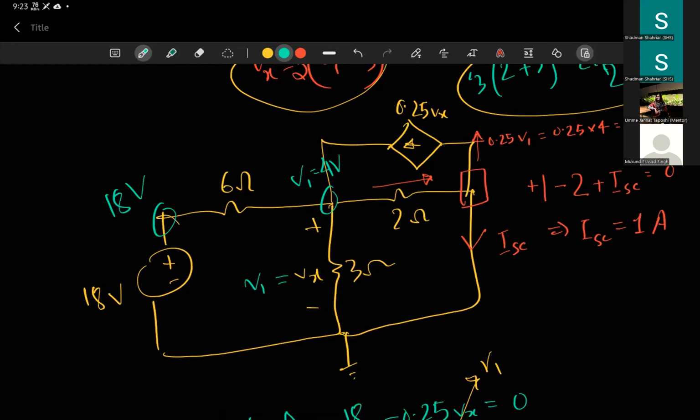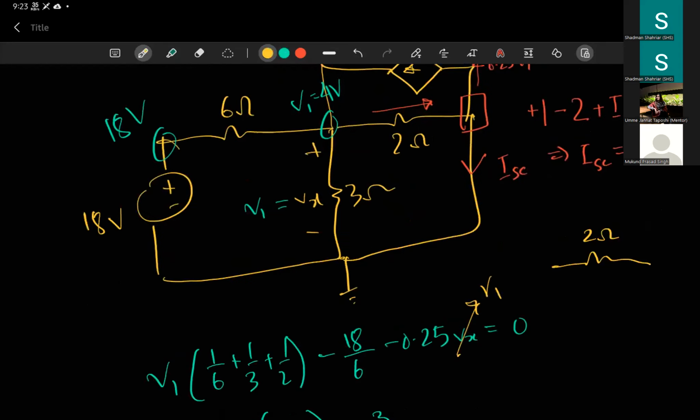The voltage here is 4 volts, right? Yes, sir. On this side. On our circuit, I'm just writing it here to focus on this. So this is connected to our ground, which means this is 0 volts, right? Yes. So what's the voltage difference? 4 minus 0. So the current is the voltage difference, 4 minus 0, divided by 2 ohm, which is 2 amperes. Okay, sir.